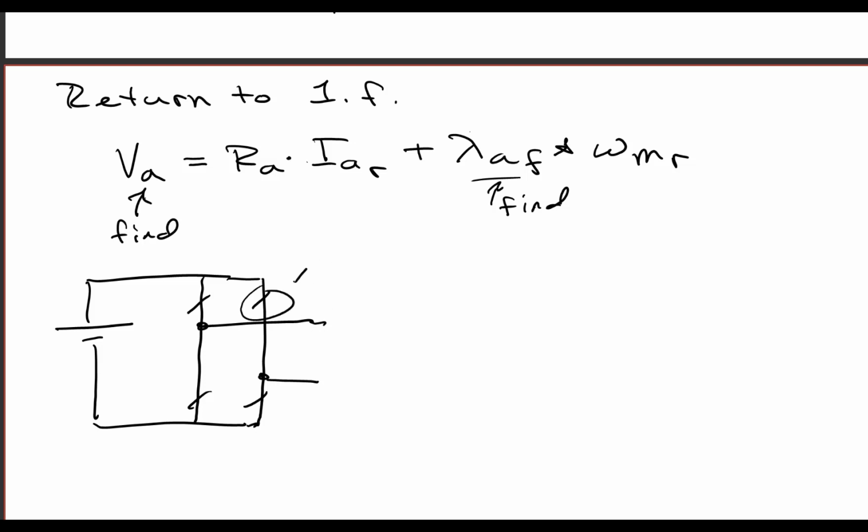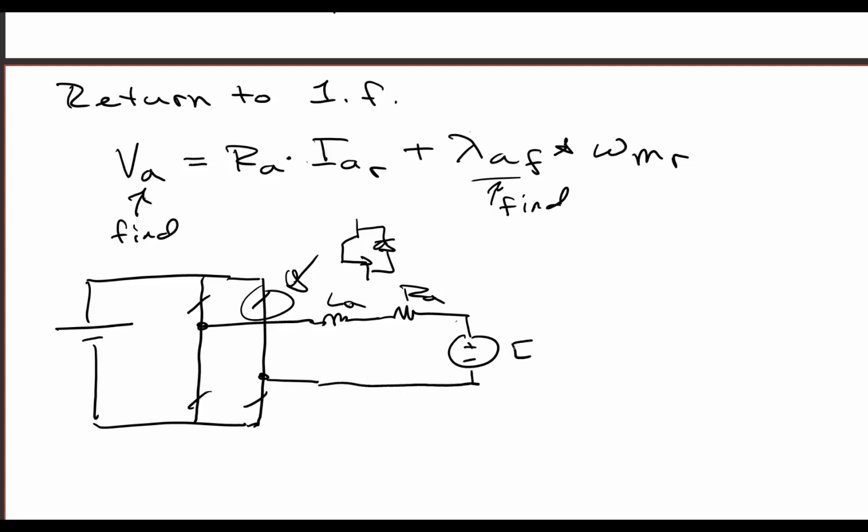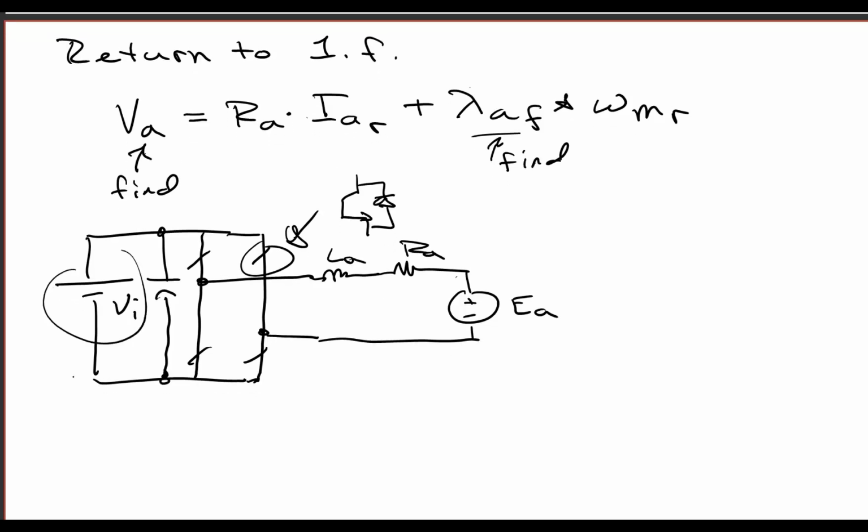just looking at it from the power electronics side. But this is my little shorthand symbol for an IGBT or a MOSFET. And then you've got some inductance there, which we ignore in the steady state. We've got the R sub A, and we have the E sub A here. We have the input voltage that's basically, if you're running off a battery, it'd be exactly that, but we know that what this really is, because you're running off of a line, right?